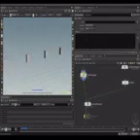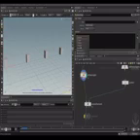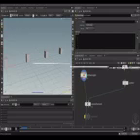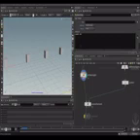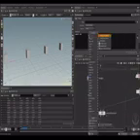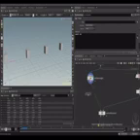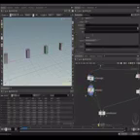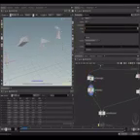It's called vector @altposition = @P, which is just making a copy of the position. And then I want to add some noise on it. So I'm going to use an attribute noise connected here and to the position. Let's enter the noise.